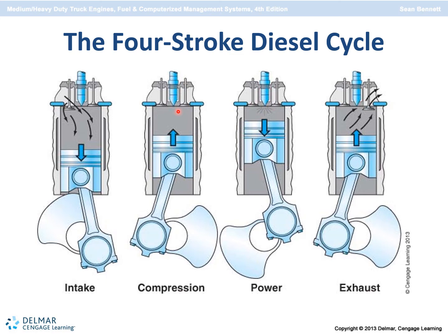Just before top dead center on the compression stroke, fuel is injected into the cylinder, and it creates the power stroke. Both valves are closed here, and in the power stroke we have effective pressure of approximately 3,000 pounds per square inch that pushes the piston down and throws the crankshaft. That's also called crankshaft throw at this point.